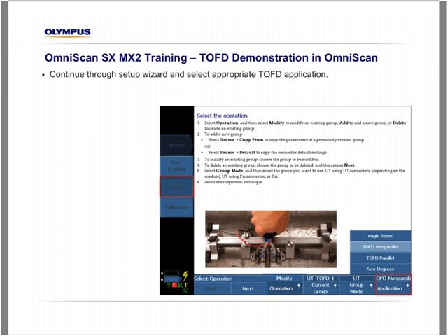The last option in the TOFD wizard at this point of the setup is either a non-parallel or parallel TOFD inspection. The parabolic cursors of the TOFD analysis functions, the algorithm used to linearize the screen, and a few mechanical issues separate these two.